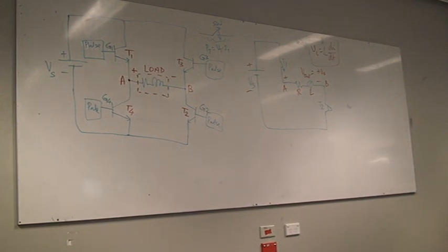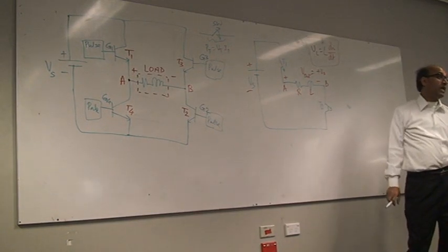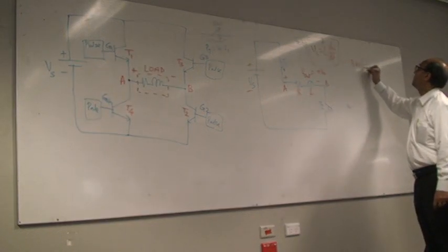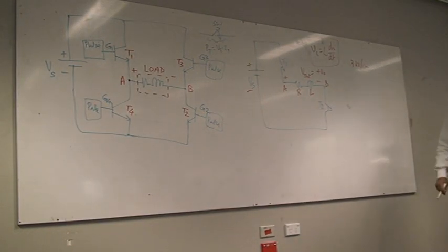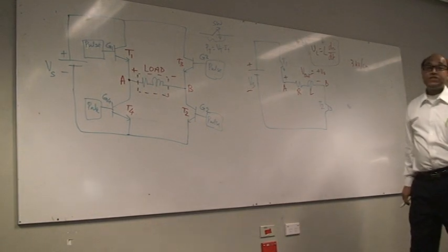So that inductor voltage, L di/dt, can ionize the air. Ionized air means 3 kilovolt per centimeter. So if you have a 1 centimeter air gap and apply 3 kilovolt, then you can actually ionize the air. Okay? So it can generate voltage.